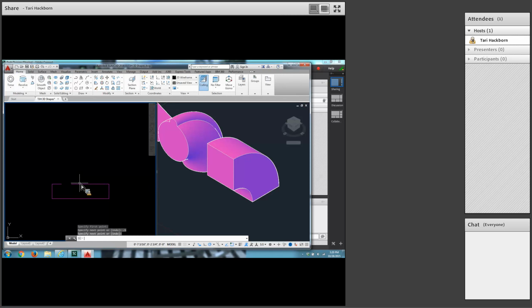Okay, that's the bottom. If you notice, the top is not the same length as the bottom. The top sticks out 1/16th of an inch farther to the left than the bottom. The bottom's 3/4, the top's 13/16. So let's offset this line up 1 1/8 because the dimension goes from this line right here. That's this one right here.